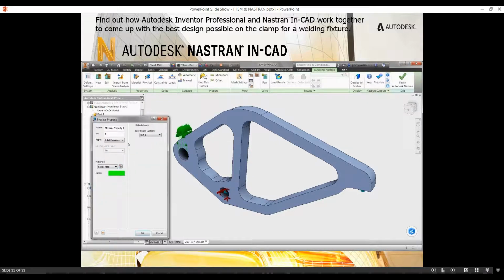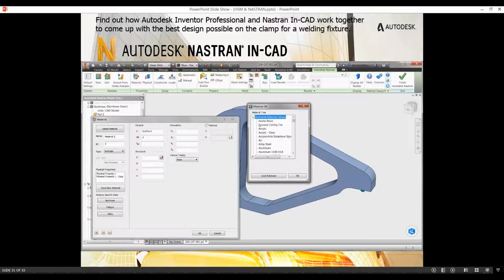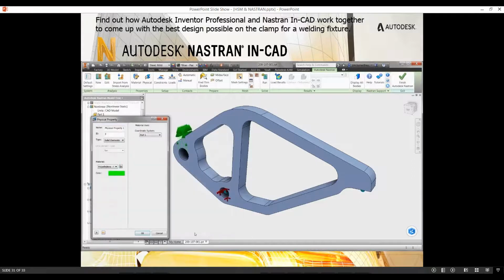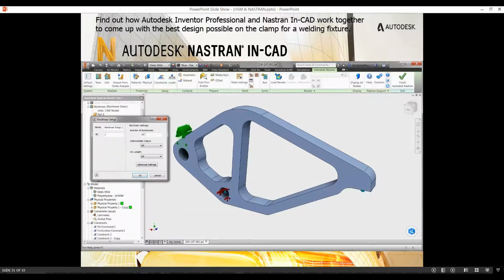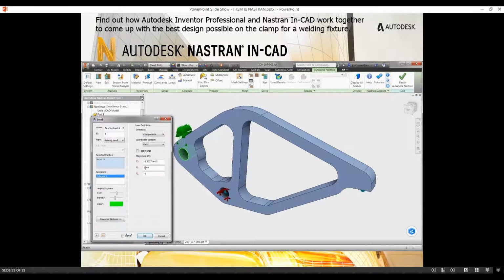Let's edit the material we used in the previous fatigue study and change it to UHMW. We will find out how much of the load it will handle before it yields or maybe even buckles. Nonlinear studies are highly accurate. We will spread the load out in 30 increments and observe the results as it is gradually applied. We will also increase the load to ensure our safety factor is at least 2.